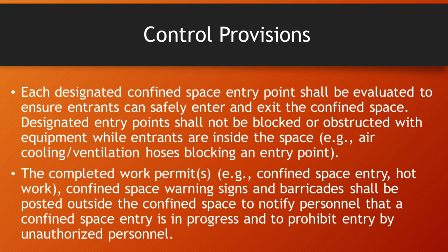Control provisions. Each designated confined space entry point shall be evaluated to ensure entrants can safely enter and exit the confined space. Designated entry points shall not be blocked or obstructed with equipment while entrants are inside the space, for example, air cooling and ventilation hoses blocking an entry point.